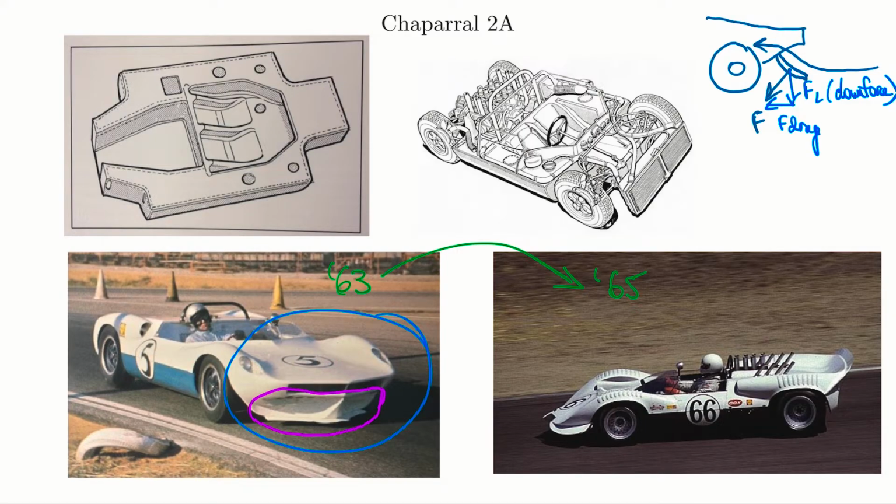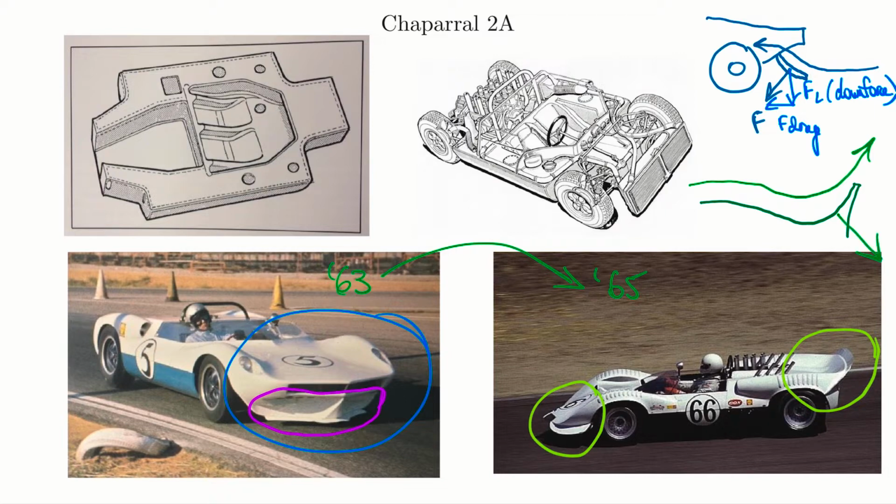And so I've shown the new one on the right here. So we can see at the front of the vehicle, they completely redesigned it now, knowing they not only want to prevent the lift at the front, but they want to actively push down on the vehicle. So they want more downforce. So we can see on these pictures of the car as well, they end up putting a spoiler. Okay, so they sort of have this little scoop type shape. And so what happens is as the air comes across and is again redirected upwards, right? So that air, instead of traveling flat now, it ends up pushing back down against the vehicle, right? And so that pushes the rear of the vehicle down as well. So you can actually get a balance now between the front and the rear of the vehicle pushing down against the tires more evenly. You need balance to get race car performance, right?